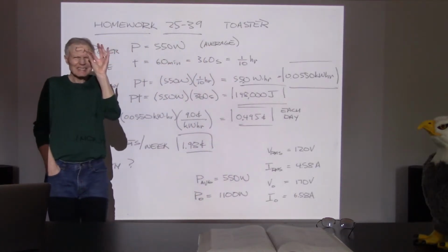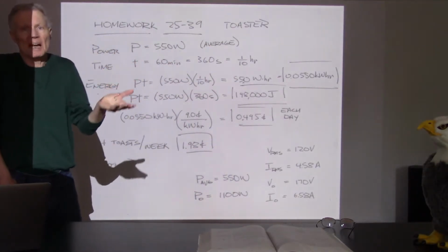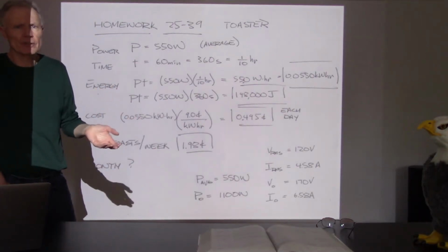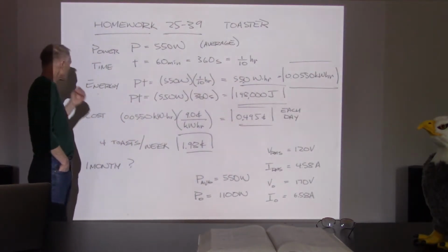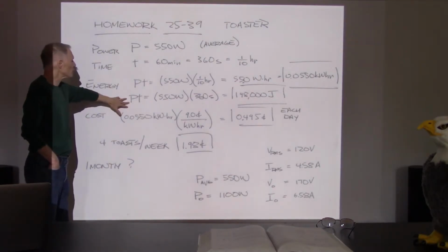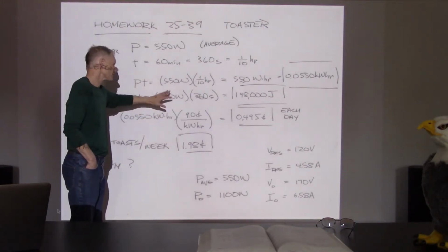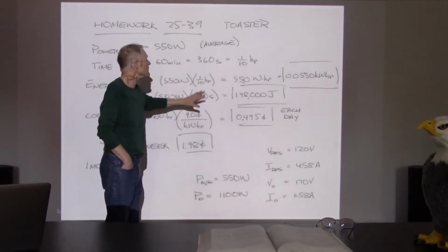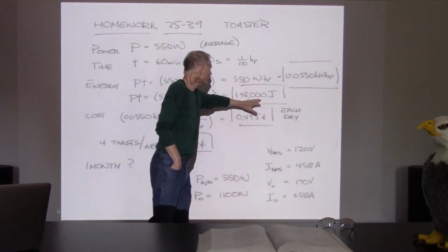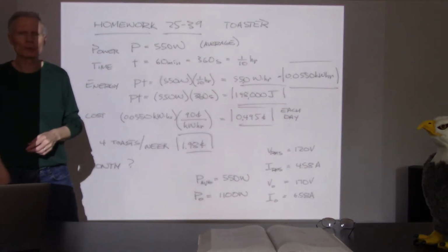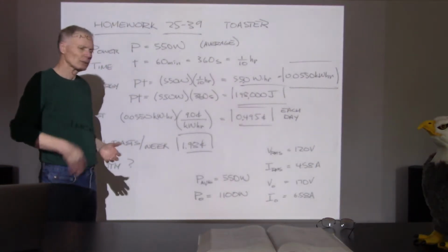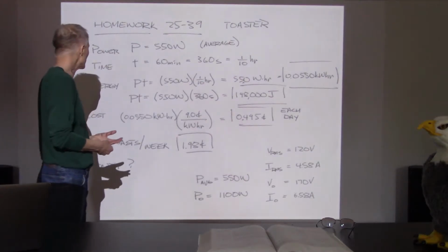It's a tiny fraction, but hey, it's a toaster. It's only on for 6 minutes, right? How much energy is that going to use? I also calculated it in joules. So 550 watts, standard units, 360 seconds, standard units, 198,000 joules, and I do like using joules for everything, I guess, so that you can do easy comparisons.